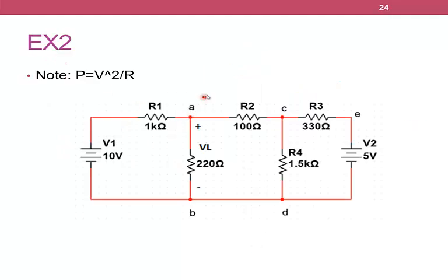For the second part of this experiment, you are going to apply Thevenin and Norton theorems. Besides the maximum power transfer to this circuit, you are going to implement it and calculate V Thevenin, I Norton, R Thevenin, and the maximum power in this circuit, as you will see inshallah next lab. Please note that power here will be calculated in another form by V square over R.